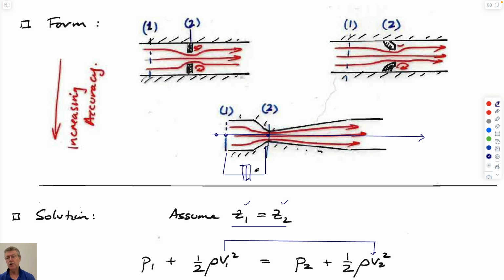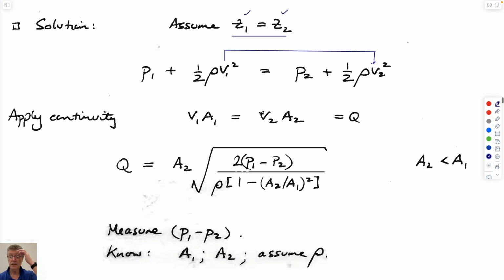It has a strain gauge on it, so that if the pressure here is higher than it is here, which it would be, then the membrane bends. You measure the bend in that membrane, and you calibrate it against upstream pressures and downstream pressures, and that gives you P1 minus P2. So if we apply Bernoulli to this, we'd substitute V1 is equal to V2 A2 over A1.